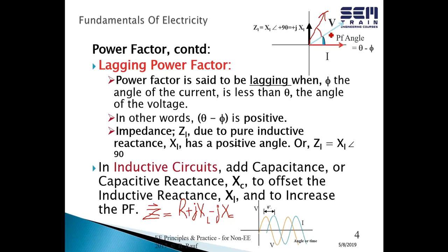correcting cap banks. The capacitors are connected in the circuit automatically, injected into the system when the power factor drops. When the power factor goes back up, those capacitors are taken out, so you're automatically monitoring the power factor and responding to it by injecting or removing capacitors automatically using PLCs or whatnot. So anyway, that's a way of looking at power factor. Another way of looking at power factor and power factor related problems, physically, practically, and also theoretically, mathematically.